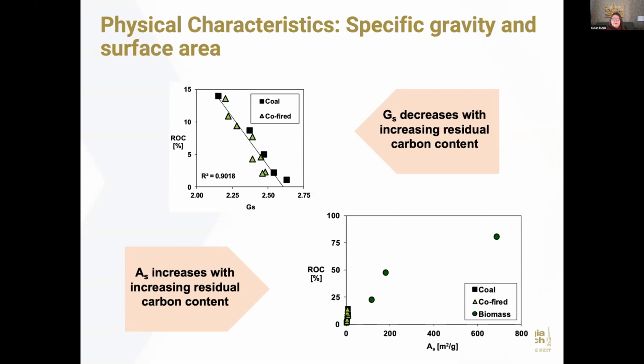Our silica particles, which you'll see a lot of times in ashes because they come in from the boiler, from the mining and the excavation, and from the storage lot, we know have a specific gravity of 2.65. So we see this nice correlation as we do a mixture between the organic and the mineral phase components.